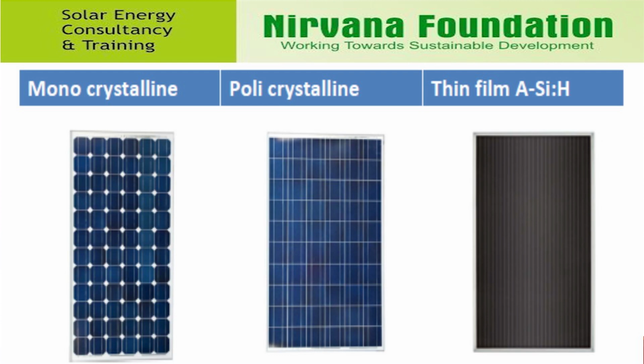To make solar cells for monocrystalline solar panels, silicon is formed into bars and cut into wafers. These types of panels are called monocrystalline to indicate that the silicon used is single crystal silicon. Because the cell is composed of a single crystal, the electrons that generate a flow of electricity have more room to move. As a result, monocrystalline panels are more efficient than their polycrystalline counterparts.